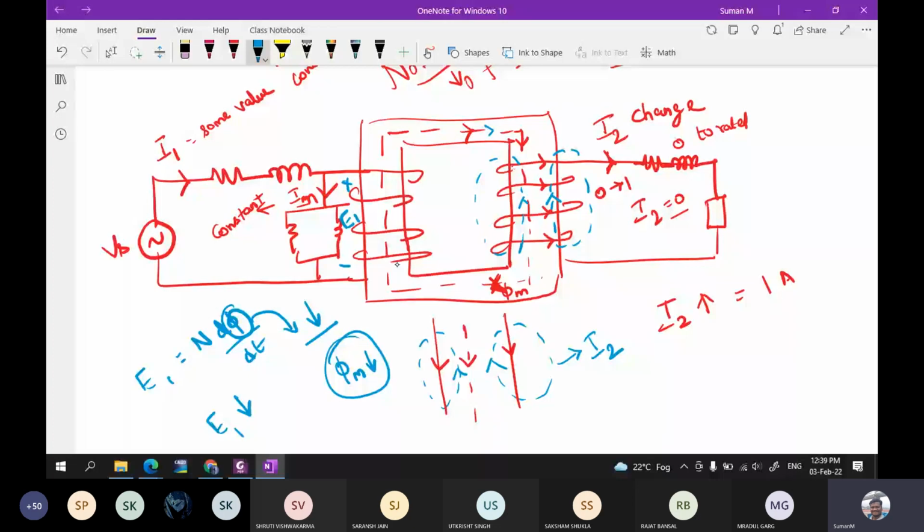Okay, the current flowing through this path, you know that if you are having two terminals, by nodal analysis you can consider if you are having V1 here and V2 here, and it is connected by some Z. For AC circuit we need Z, for DC circuit we will be using R. When we are saying nodal analysis, the current flowing through this path is given by V1 minus V2 divided by R. So for AC circuit we have to write it as V1 minus V2 divided by Z. So now the current flowing through this path is given by difference in voltage divided by impedance.